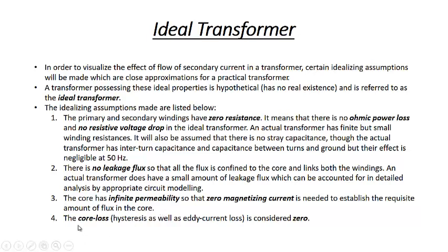One more thing, the core loss, that is hysteresis as well as eddy current loss, is considered to be zero. So these are the four important assumptions that we make for a transformer to be an ideal transformer.